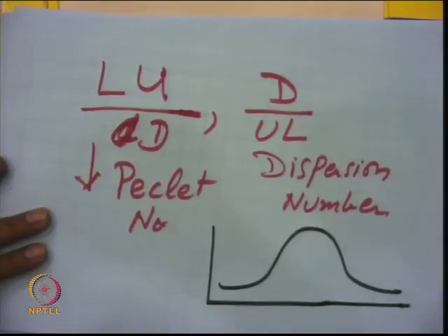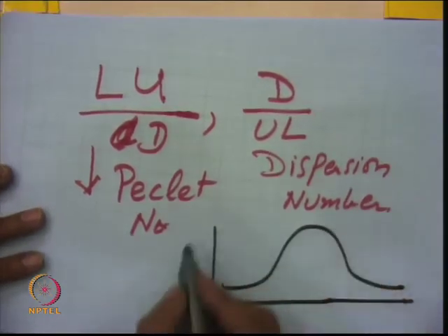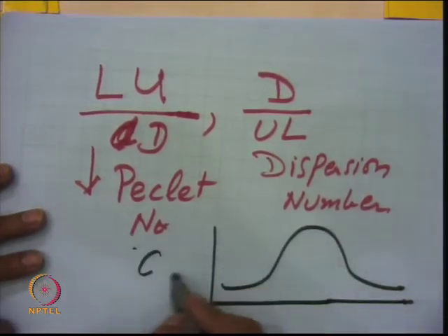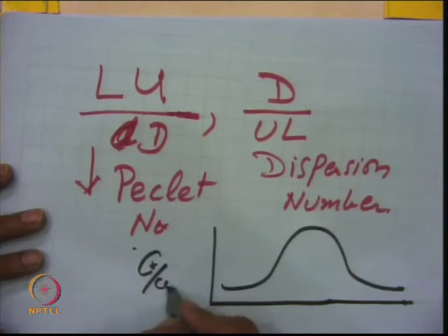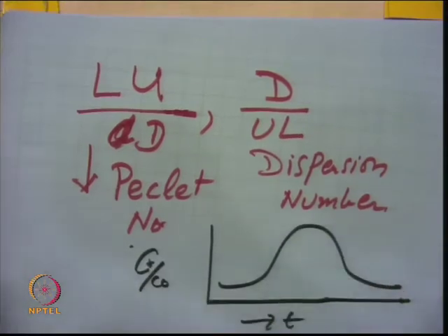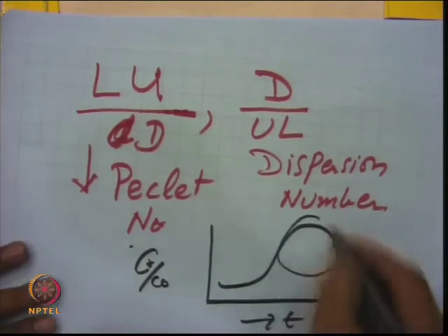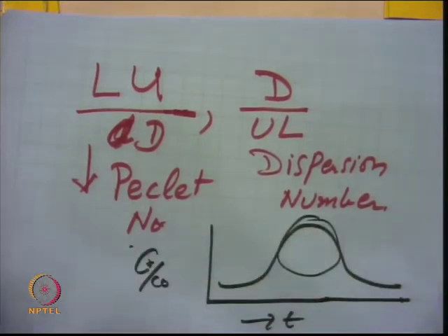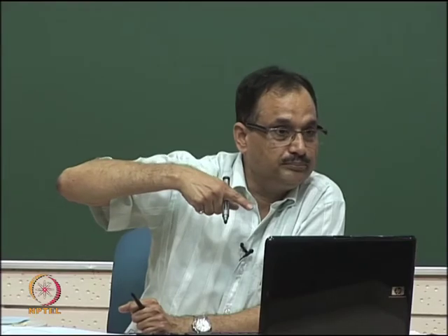By residence time distribution, one can see a profile like this. If I measure the dimensionless concentration C_t/C_0 versus time, the exit concentration will come at some time; the maximum concentration will arrive at the mean residence time, which is similar to your W/F_A0.